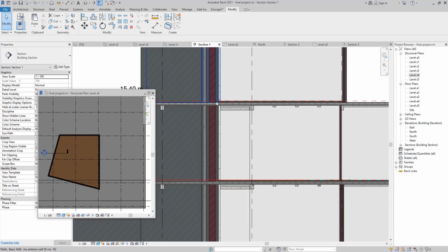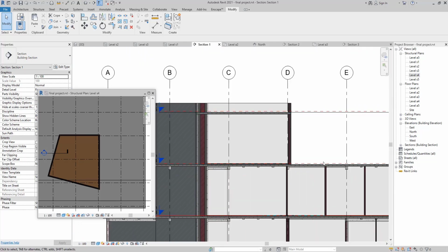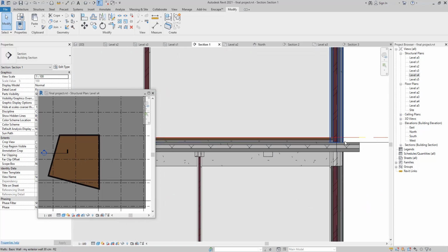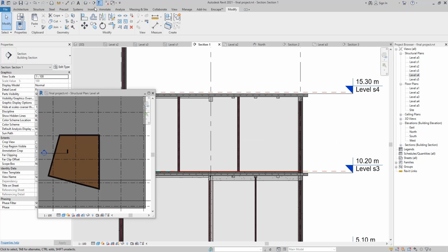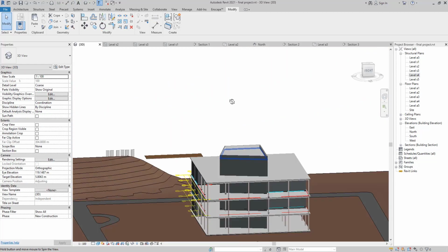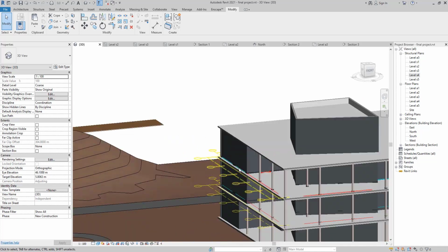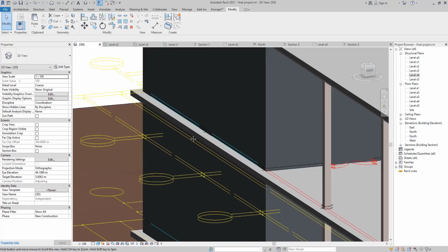So the next step is to check if we, since we didn't copy paste our wall, or we didn't paste the floor, we don't need to do this action right now, but we are supposed to go to our 3D view and edit our view, because it's wrong. We are not supposed to have our structure floor like this.